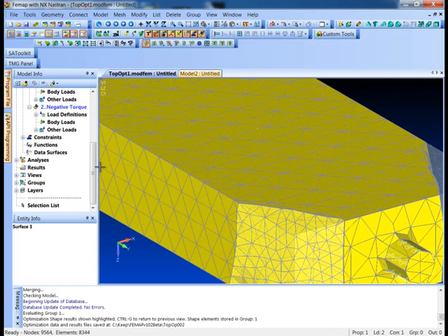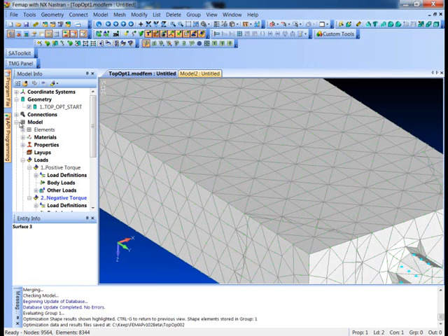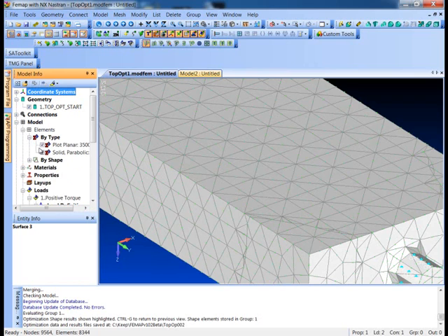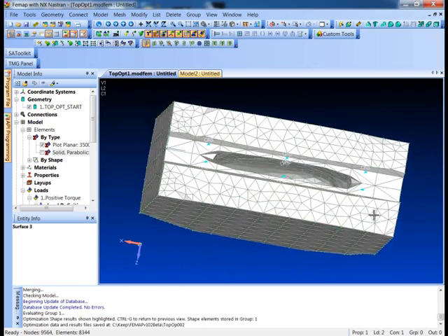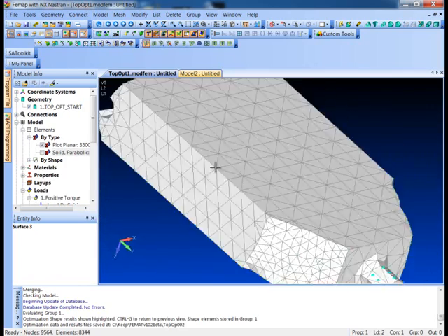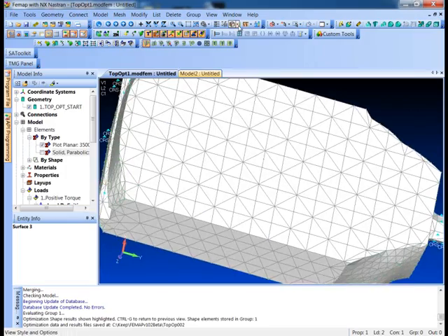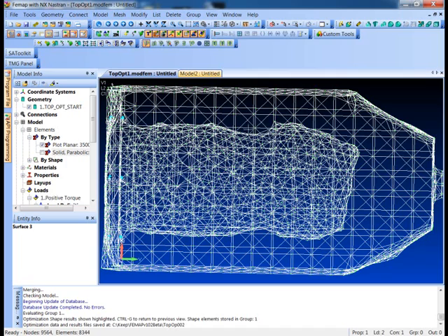So what we've done is we brought in here, these are plot-only elements in FEMAP. They're just highlighted right now. So I'll go ahead and redraw the display. But we can use some of the visualization tools in FEMAP. I'm just going to turn off the original solid elements. I'm looking at just the resulting topology optimized mesh or shape, and actually go into a wireframe view, and you can see that it's showing us how to carve this out up the middle.